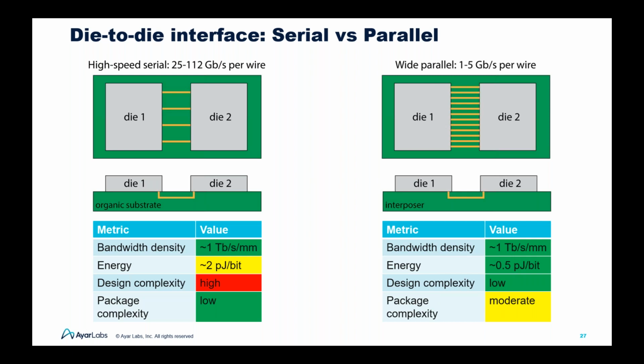I think still, if you want to push it to using serial link and do some kind of clock forwarding, you're going to still get something close to 1.2, 1.5 picojoules per bit. But the other thing, though, as well, in design complexity, it's the same. It's just you're pushing it into your chiplet rather than being in the processor die.